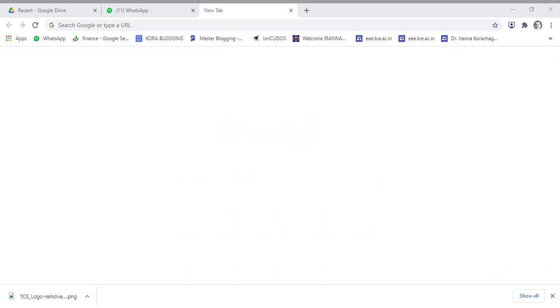The next keyword is: we apply rated current at rated frequency. Rated current and rated frequency is one word, and of course, associated with that, the circuit breaker contacts are to be closed. That is common sense.